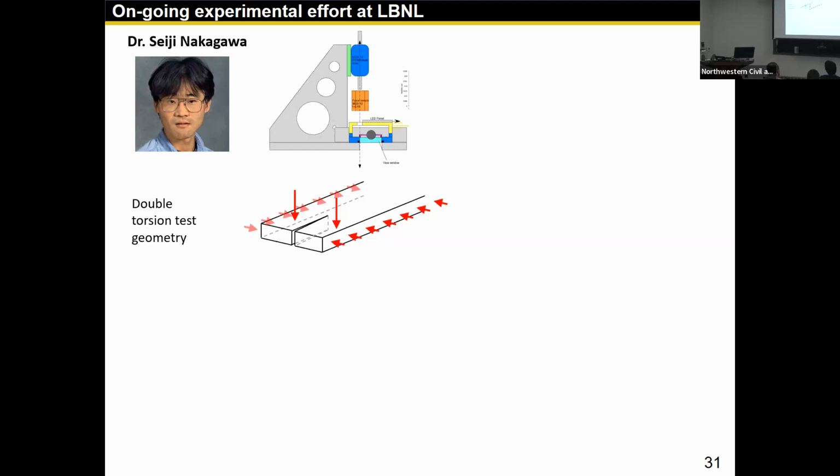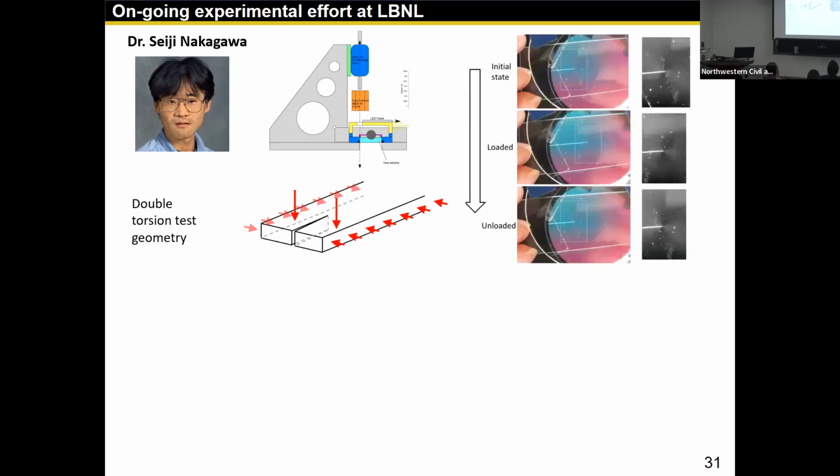And he opened up windows to let the light propagate through the specimen in hope to capture some photoelastic effect. So he can propagate polarized light. Here it's just very preliminary data. If you look at black and white, you can see indeed the fringe pattern, which highlights the stress concentration, coincide with the optical crack tip, which nobody confirmed before. Maybe is the optical crack tip the real crack tip or not? Is it the real location of the stress concentration or not?